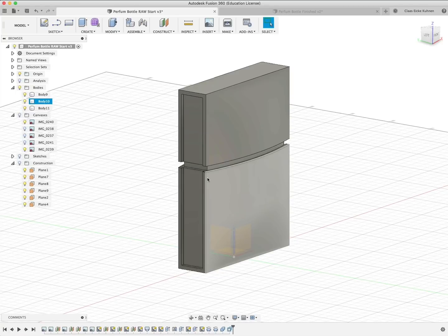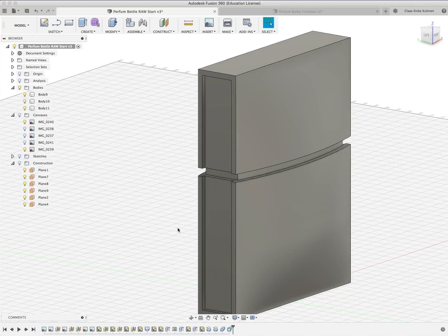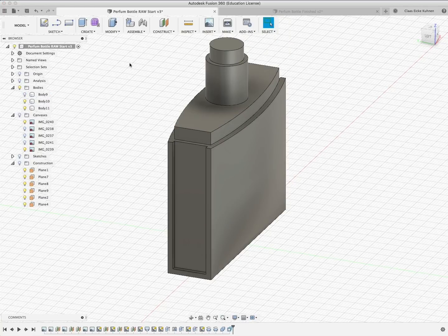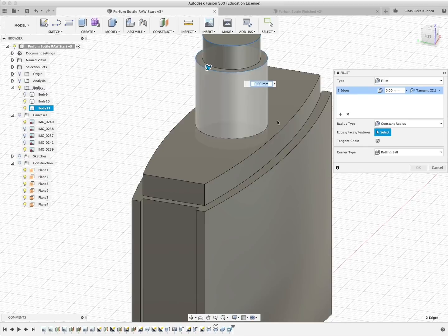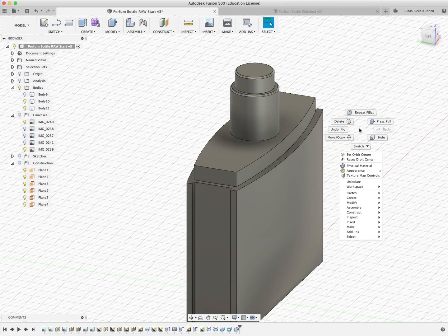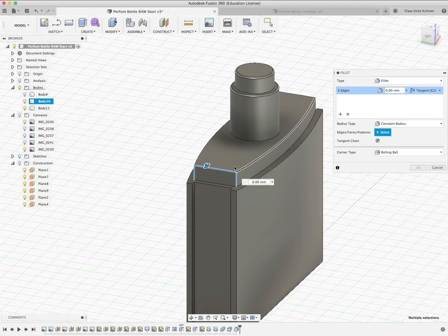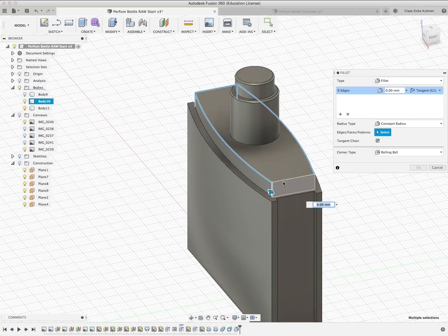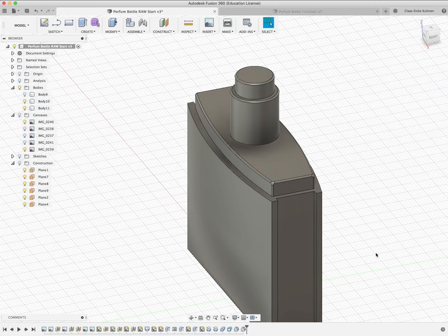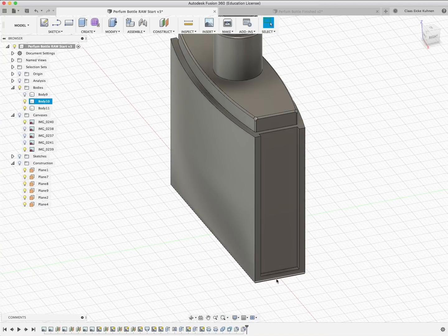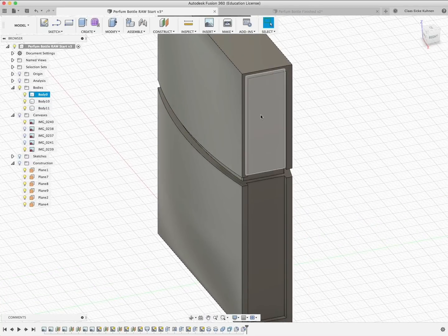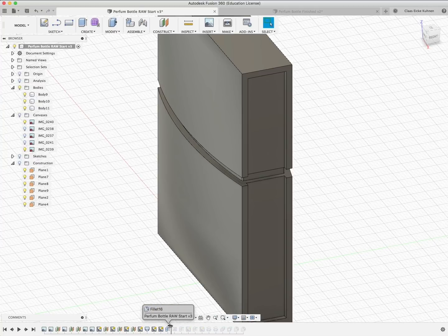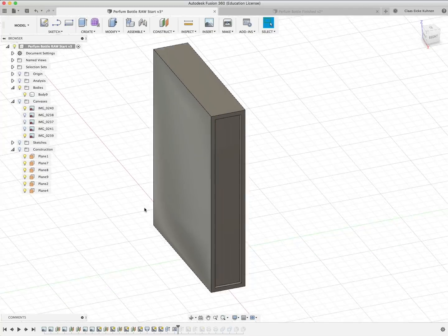So this is now a point where most of these elements are kind of built. I could go in now to add all the fillets, and here I have to be pretty careful about how I do this. So also here I try to have a good logic. Maybe these two I select and say 0.5. I could select all these edges here together. There, 0.52, but I would like to have a setback corner. Very nice. Now these corners I would like to fillet too, but let's say I would like to do this at the same time when I have this actually not cut yet. So let's go to there. Okay.